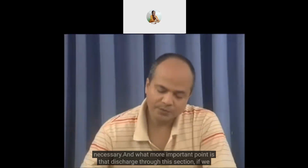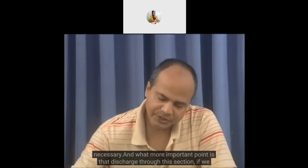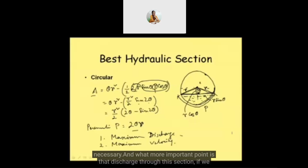What is more important is that when we try to find the discharge through this section, many a time our objective is to have maximum discharge through the channel, and many a time our objective is to have maximum velocity through the circular section, so that we can avoid siltation in the channel. In a circular section, maximum velocity and maximum discharge are not the same, they do not give us the same value.